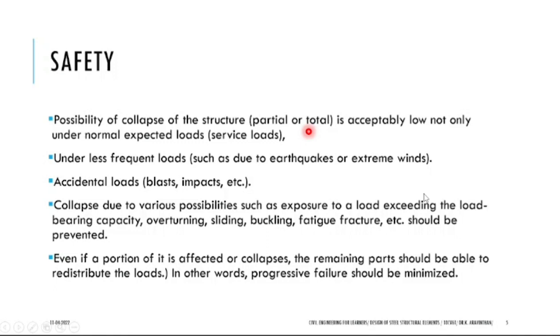What should happen is, the first indication it should give is cracks, and the next indication it should have is excessive deflection. What do you mean by excessive deflection? The code suggests L by 300. L is the span, 300 is the constant. So if you have 10 meters of span, what is L by 300? 10,000 divided by 300 is what? 33.3, yes. So your structure will have a deflection of 33 mm, that is 3 centimeters.